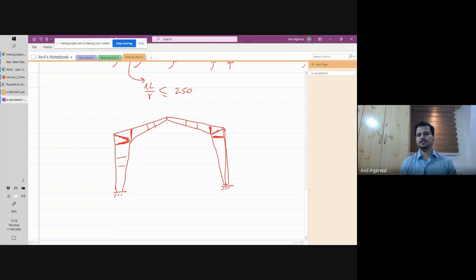So basically, the way these are made, these are not hot rolled sections. These are I-beams, but these are tapered I-beams. So basically these are plate girders. So they take one plate. These are basically plate girders which are welded together. So they do the welding.